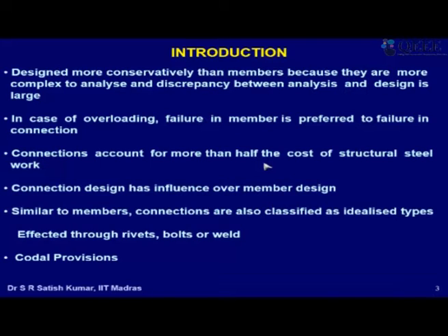Then of course connection design has influence over member design. We have seen, for example, in single angle tension members, the length of the connection controls the shear lag. Or in single angle compression members, the number of bolts controls the effective slenderness ratio. So all these factors become very important.